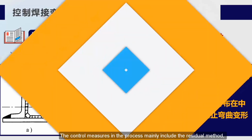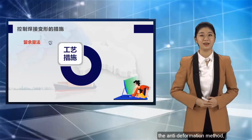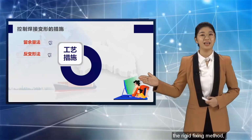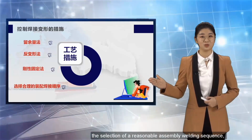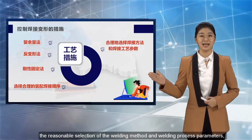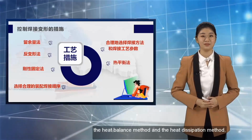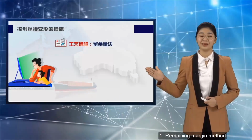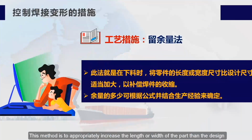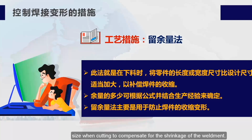The control measures in the process mainly include the remaining margin method, the anti-deformation method, the rigid fixing method, the selection of a reasonable assembly welding sequence, the reasonable selection of the welding method and welding process parameters, the heat balance method and the heat dissipation method. 1. Remaining margin method. This method is to appropriately increase the length or width of the part than the design size when cutting to compensate for the shrinkage of the weldment.